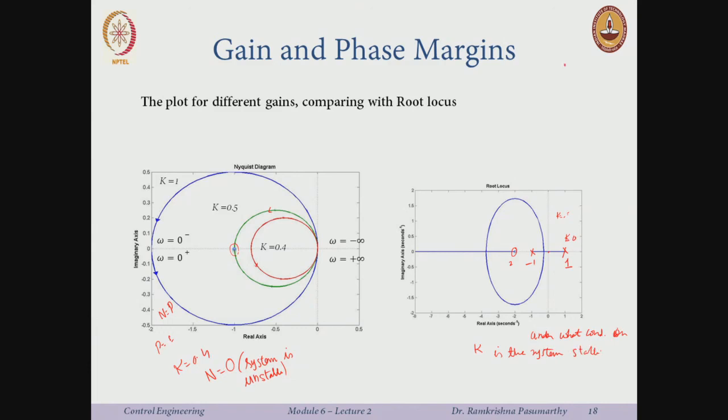Usually, okay, let us then do something else. Say I have a system with a pole at -1, a pole at -2, a pole at -3, and there are no zeros, and I will just do all the rules of the root locus. One branch will go to infinity this way, and these two will meet here and then go this way. There is some value of gain k, let us say k prime, and this is k equal to 0.